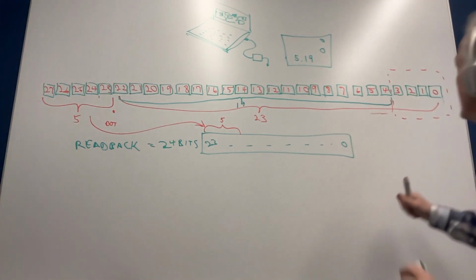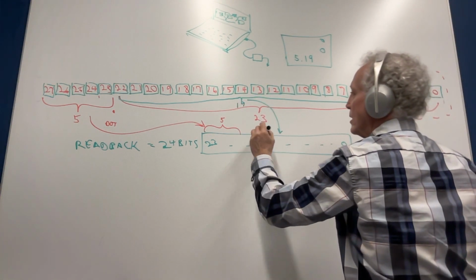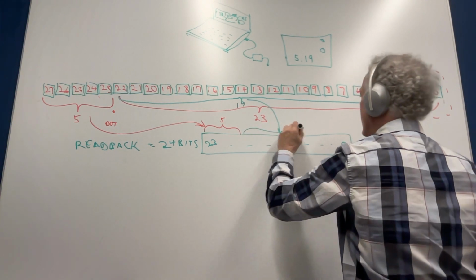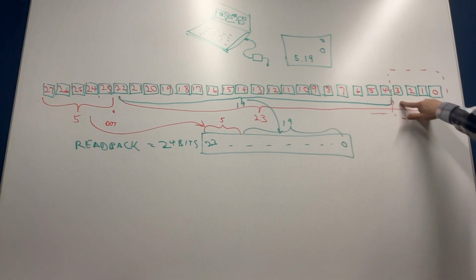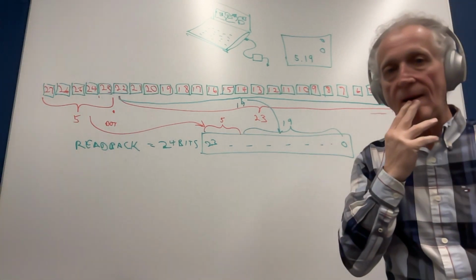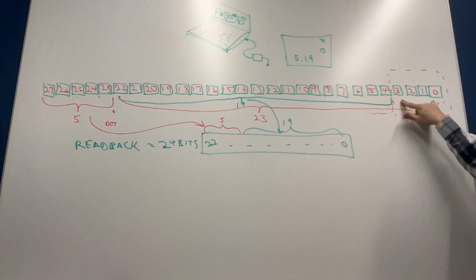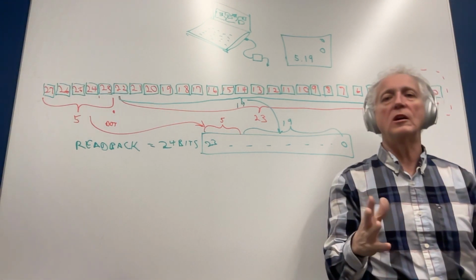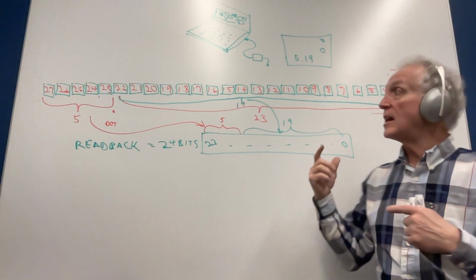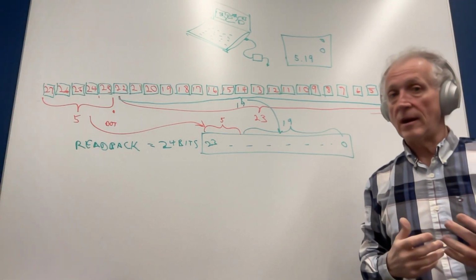19 digits. If we count it out, it'd be 19. We take that and we move it here to 19. So we're not going to take the bottom 4 LSBs. They get truncated. So when we're doing a read back, we're not going to see these 4 bits. This becomes very important when we're dealing with integers, when we're dealing with cells that use these bits and we want to see them. We're not going to be able to see them.